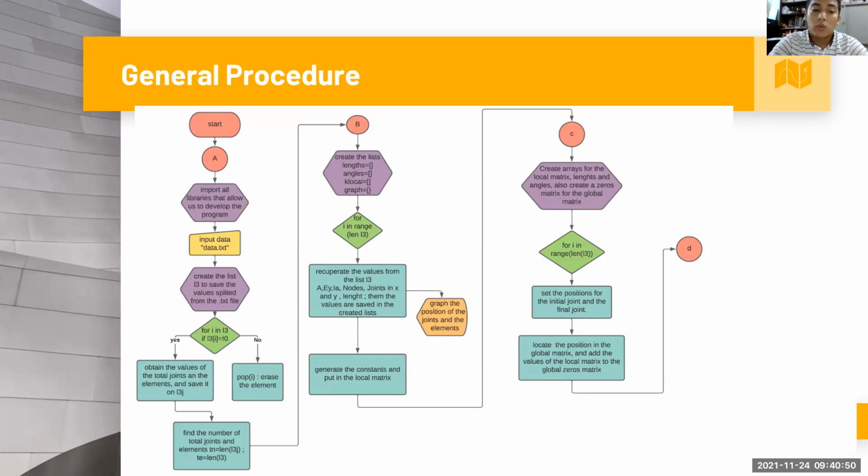It's important to emphasize that the stiffness matrix for this case will be for a two-dimensional, arbitrarily oriented beam element. Particularly, the stiffness matrix of each element can be assembled into a global matrix, which defines how the entire structure will deform when the load is applied to it. Each local matrix has to be located based on how the elements are connected together, according to the continuity principle. Then a system of equations can be created.